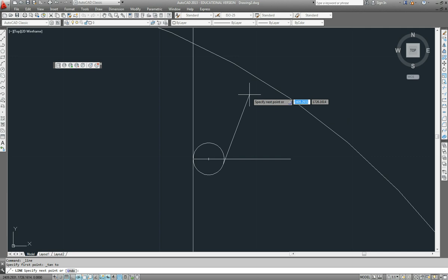We know an angle, we know a rough distance, let's say relative to our starting point, so at a distance of, don't know, let's say 20, at an angle of, and that will be 90 minus 10, which is 80 degrees. So that's the center line of our tooth.